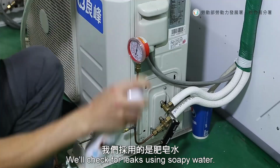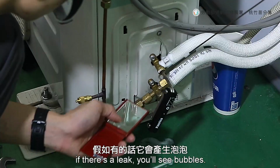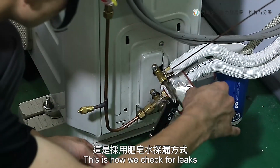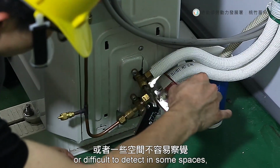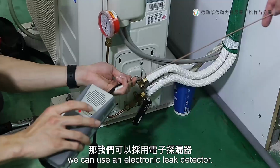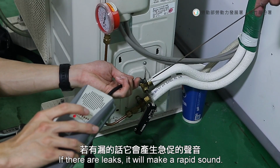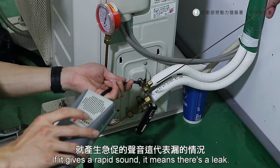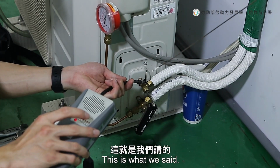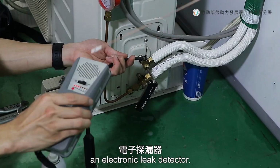We'll check for leaks using soapy water. When we check for leaks, if there's a leak, you will see bubbles. This is how we check for leaks. If the leaks are very small or difficult to detect in some spaces, you can use an electronic leak detector. If there are leaks, it will make a rapid sound. Alright, if it gives a rapid sound, it means there's a leak. This is what we set. Aside from using soapy water for leak detection, we can also use an electronic leak detector.